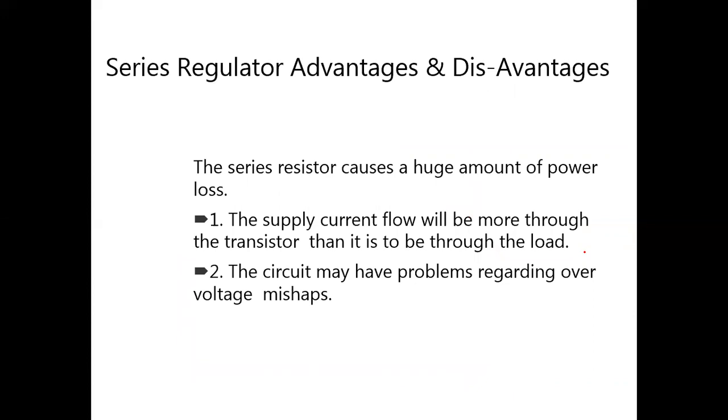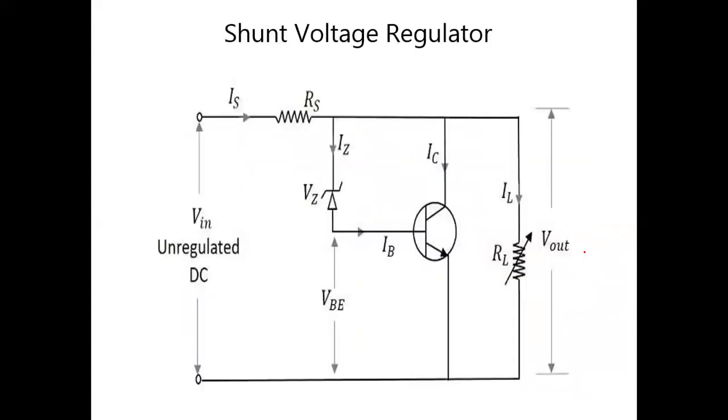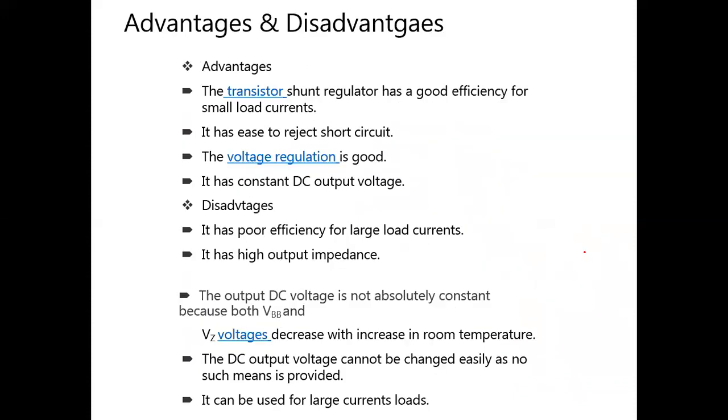So the advantages and disadvantages of the series voltage regulator. The series resistor causes a huge amount of power loss. The supply current flow will be more through the transistor than through the load. The circuit may have problems regarding overvoltage. So these are the models used in the concept. These are the advantages and disadvantages.